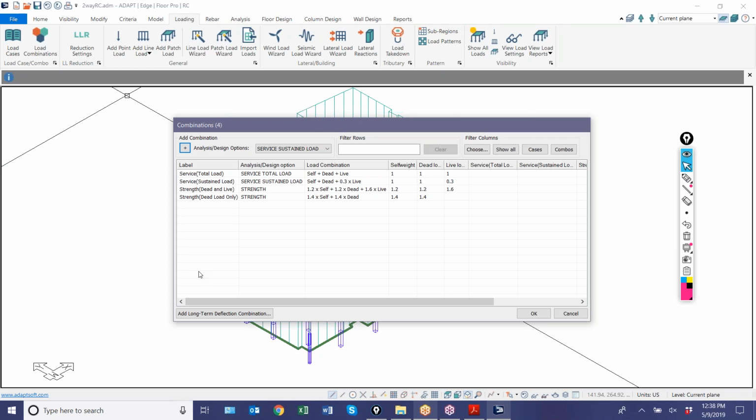And obviously we don't have control over how complex a model is or how simplified it is. But let's just say it's above average complexity and it's a multi-story model and it's 20 stories. And now when you analyze and you mesh, the mesh size is pretty condensed because of the complexity, and you have 70,000 nodes in the model that are being solved for 400 combinations. That can become a performance issue.